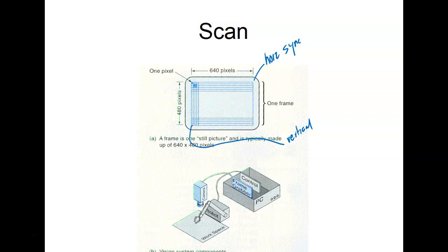These are really old, and they wouldn't be compatible now, but we had to synchronize these. The problem is that the tuning circuits were made out of components that varied with temperature, capacitors and inductors. Now we use things called phase-lock loops, and we don't have to worry about that. So I don't remember the last time I've seen a monitor go out of sync with the actual cameras themselves.